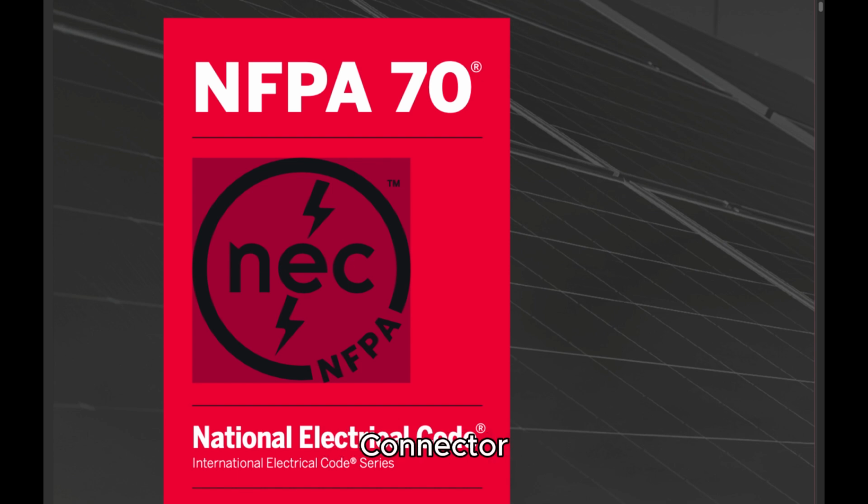CMP6 cord connector. As applied to hazardous classified locations. A fitting intended to terminate a cord to a box or similar device and reduce the strain at points of termination, and may include an explosionproof, a dust ignition-proof, or a flameproof seal. CMP14 cutout box. An enclosure designed for surface mounting that has swing doors or covers secured directly to and telescoping with the walls of the enclosure.